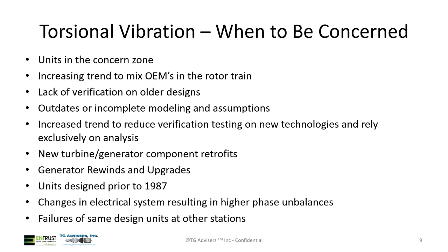And then generator rewinds and uprates. So if you're making changes to the generator rotor, or you're very close on frequencies, you may want to have some considerations there. And then 1987, units prior to 87. So that's when torsional frequencies were really starting to get understood in the industry amongst all the OEMs.